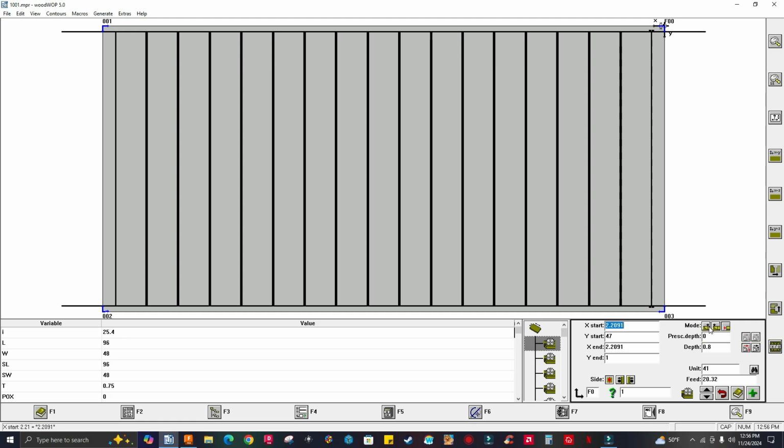This is the default in the Woodwop post processor from Autodesk. I happened to change that from this mode to the last one, which is the groove has the length plus security distance. So I made that change in the post processor. If you want me to show how I did that, I'll make a separate quick video on how you can change the mode in the post processor.